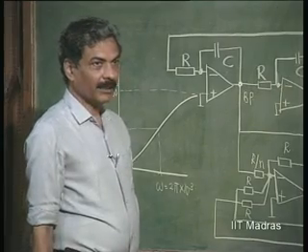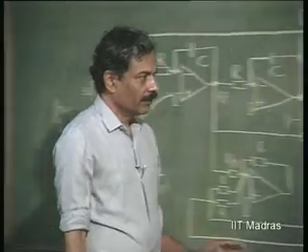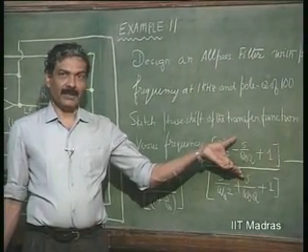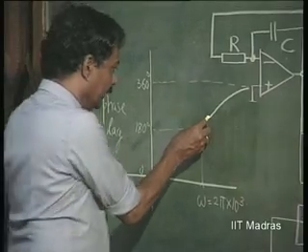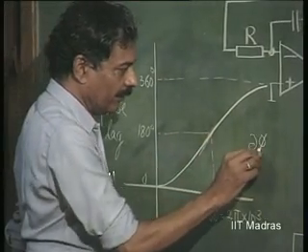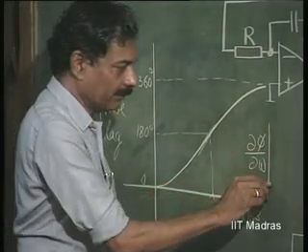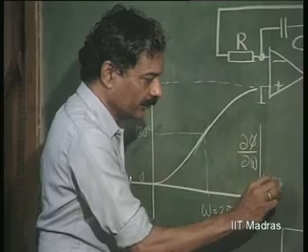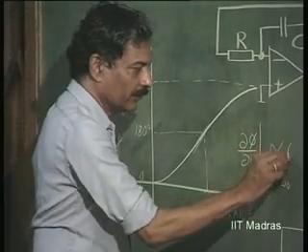So, this is going to occur at the pole frequency, this phase shift of 90 degrees contributed by the pole, 90 degrees contributed by the zero, 180 degrees is going to occur at this, and it can be shown that the phase variation, that is delta phi by delta omega, is maximum at omega equal to omega naught, and it is directly proportional to Q.